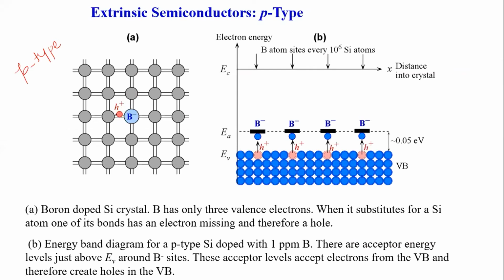One bond is left behind within the neighbors of the silicon. In the band structure, this will form just above the top of the valence band, and this atom, which is ready to accept an electron to form the bonding, is called an acceptor.